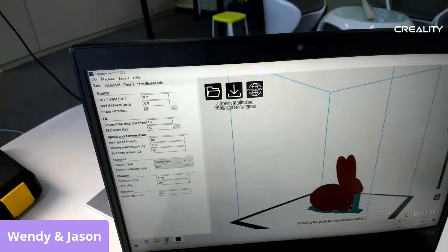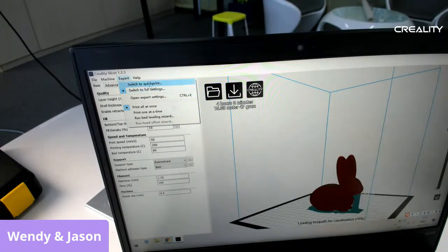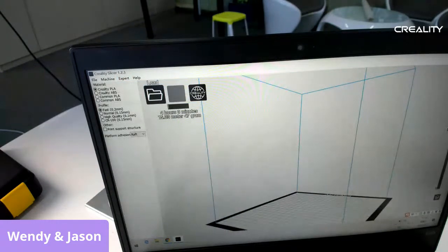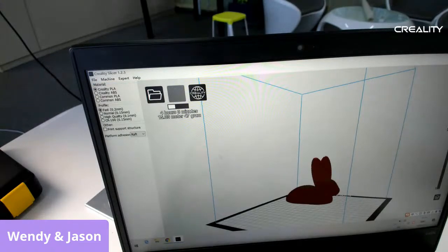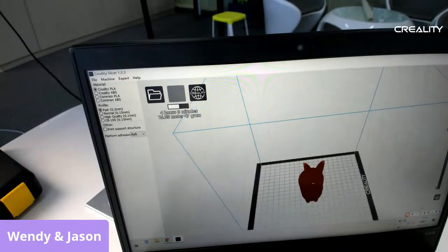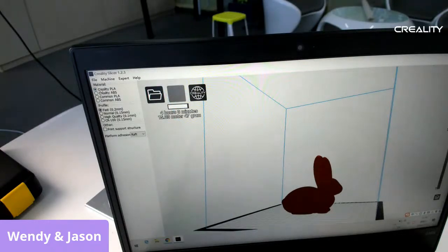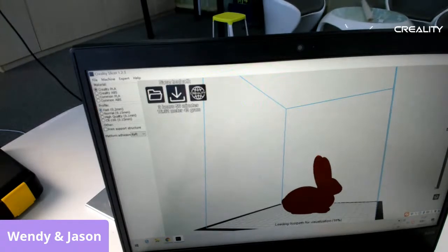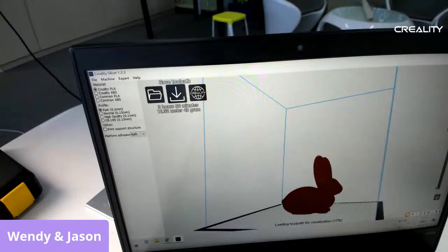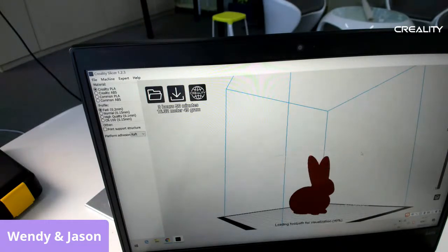Yeah, pretty easy. So now for people like Wendy who never sliced or printed anything before, there we go. Just switch to the quick print mode. The hard, complicated settings are gone. Now it just leaves you a pretty brief, simple, user-friendly screen mode. There's the material profile, which is how fast or how good we want this print to be, and this add support option, and that's it.